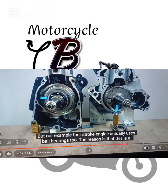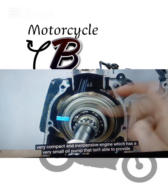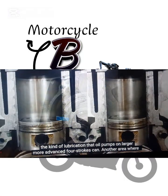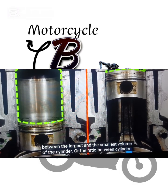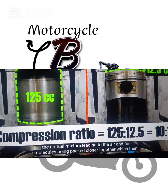But our example four-stroke engine actually uses ball bearings too. The reason is that this is a very compact and inexpensive engine which has a very small oil pump that isn't able to provide the kind of lubrication that oil pumps on the larger, more advanced four-strokes can. Another area where two-strokes are limited is the compression ratio. The compression ratio of the engine is the ratio between the largest and the smallest volume of the cylinder, or the ratio between cylinder volumes when the piston is at bottom and top dead center. The higher this ratio, the more we compress the air-fuel mixture, leading to the air and fuel molecules being packed closer together, which then improves combustion speed and strength, leading to higher efficiency and power.